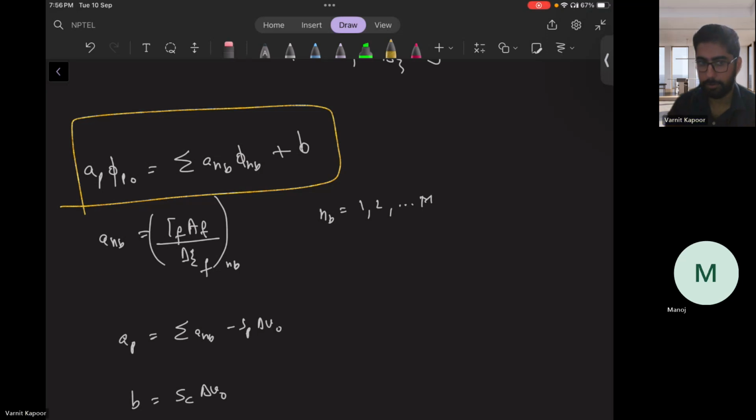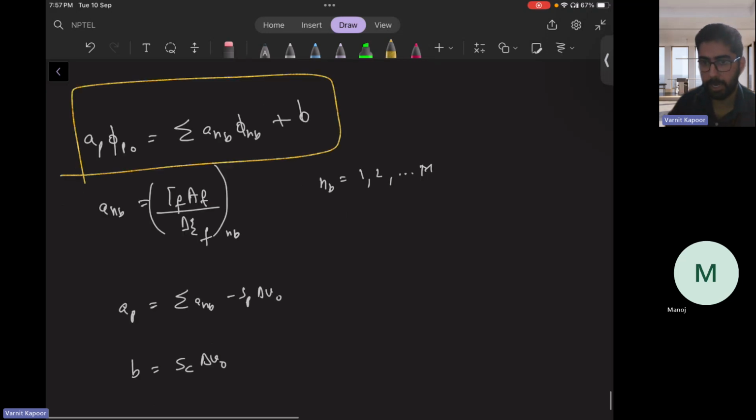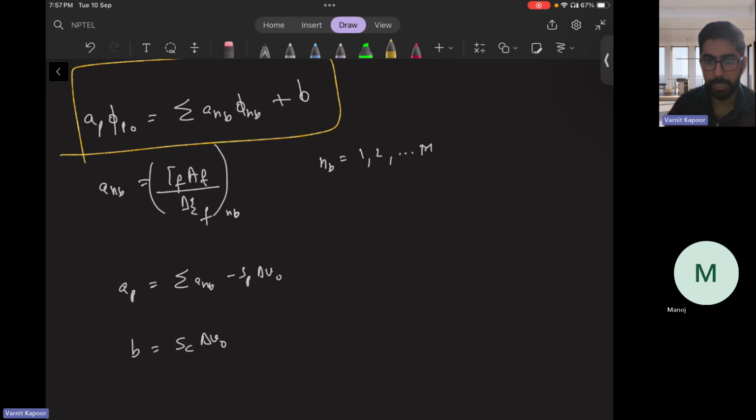No, because we don't have a structured mesh. So we cannot apply line by line TDMA. Of course, we can create some kind of line and probably do it, but Gauss-Seidel is more preferred in unstructured meshes, and it has no assumptions on structure. We can have an unstructured mesh, but it has to be orthogonal, because right now we have dealt with the orthogonal mesh. We will discuss non-orthogonal unstructured meshes in the coming tutorials.